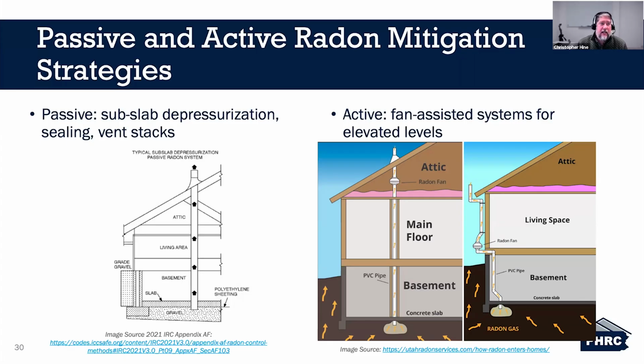When looking at the builders that are installing the passive system, oftentimes they're installing an outlet in the attic for this centrifugal fan to be installed in line of that stack unit that then draws air from under the slab and exhausts it through the roof.